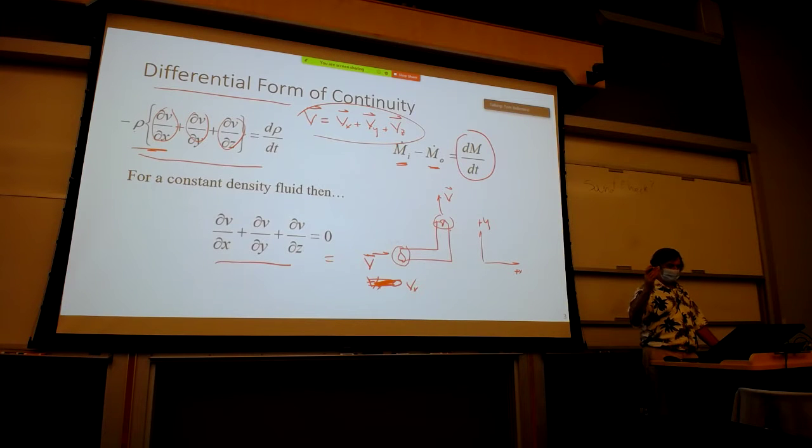Because this elbow, 90-degree elbow, is perfectly aligned with the x and the y, at the outlet, Vx is 0. So here you have dVx is actually going from Vx to 0, and similarly, at the inlet, Vy is 0, and it's some value Vy when you're leaving.